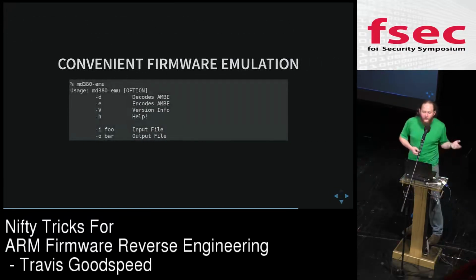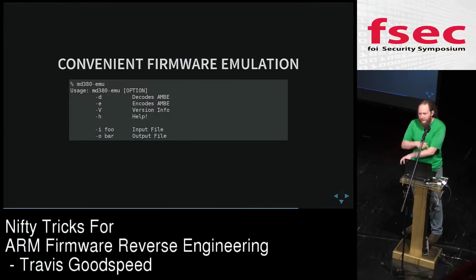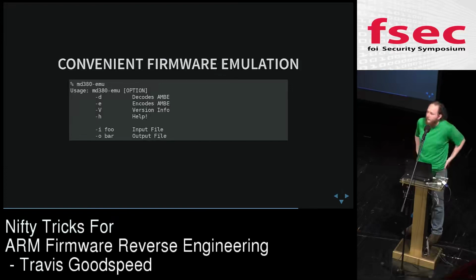Now, you also want to do firmware emulation, because when you have a firmware image and you're changing it, you need test cases or you will break your features. At the same time, you don't want to have to run it in the physical hardware, because that requires that a human being sit down, take a laptop, take a radio, plug the cable in, install the firmware, and then repeat it for each of the other 3 revisions in order to find out at the end that a feature broke a month ago.